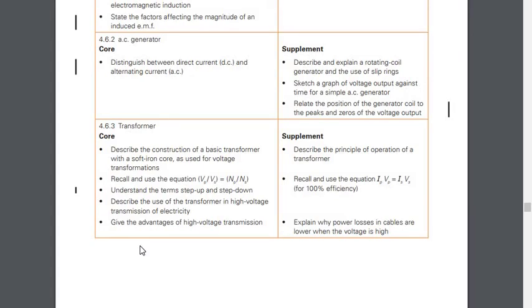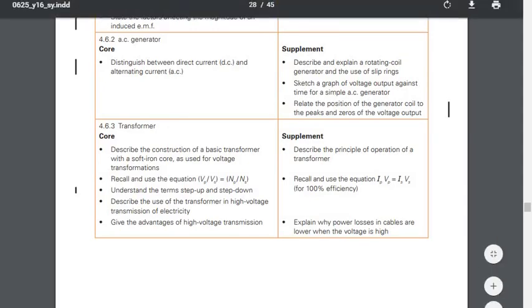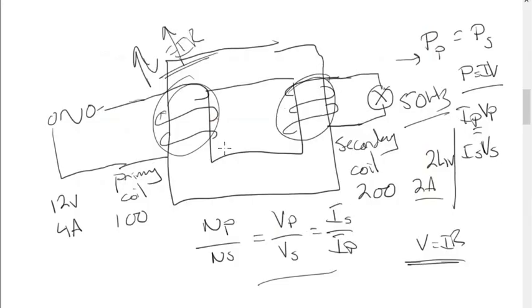Yes. Well, you're conserving power. So the power into a transformer must be equal to the power out of a transformer. Right? So if I automatically increase the voltage by increasing the number of turns, এটা বাড়তে হবে due to Faraday's law. Number of turns বাড়াই দিচ্ছি, voltage বাড়তে হবে. But I cannot just create power out of nowhere. So তাহলে কি হবে? To have the same amount of power, if I increase the voltage by a certain factor, the current must decrease by a certain factor.